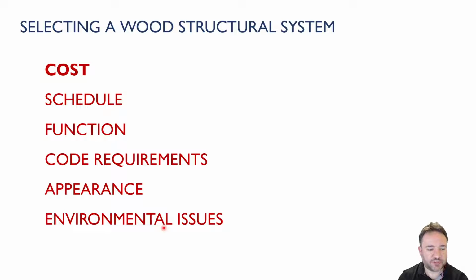The other thing that's affecting wood construction right now very much is the rapidly changing codes in this area. So now more of these things are included in the code and permitted by the code, whereas in the very early days, you really needed to do exceptions to the code by doing an alternate solutions process in order to get your local building officials to sign off on whatever it is that you're trying to build out of timber.